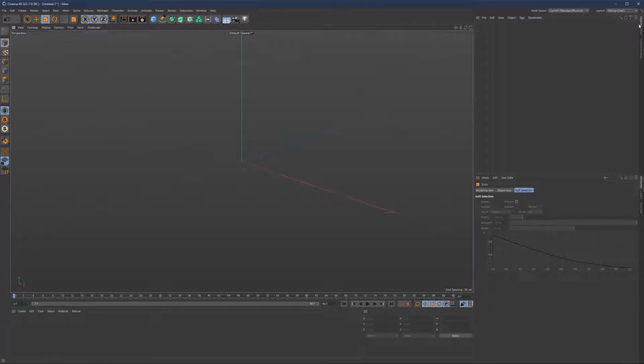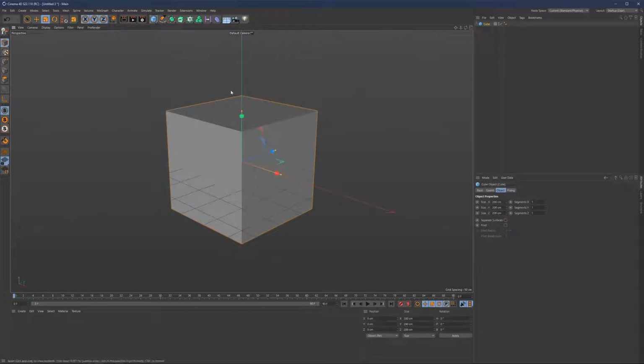And then we have here Object Manager. In Object Manager, you're going to have stored every single object that you find here in the scene. For example, if I now simply click on the cube once, it's going to appear here, and since it's highlighted, it's going to also be shown in the attribute manager as well. Whatever you have selected or highlighted in the viewport is going to be shown in the attribute manager. We can change additional parameters, like in this case, size on all axes, segments, and so on. Next to the cube, maybe worth mentioning here, you're going to see this little green check mark.